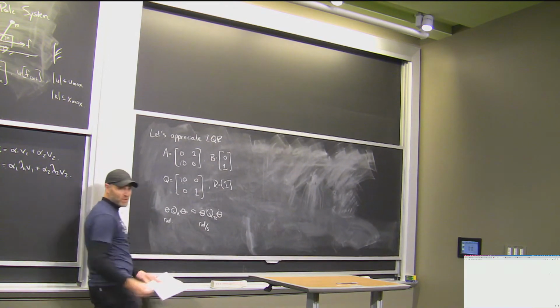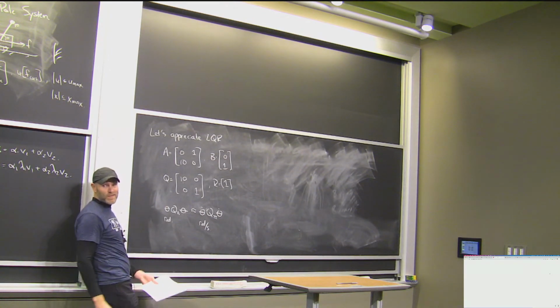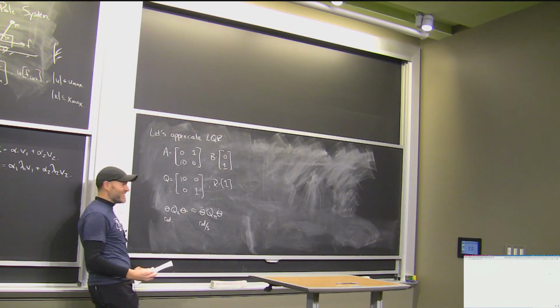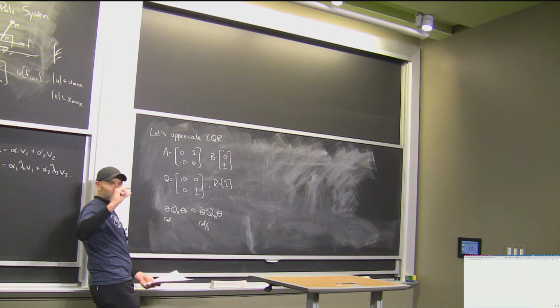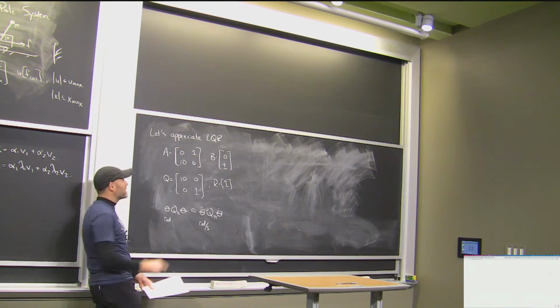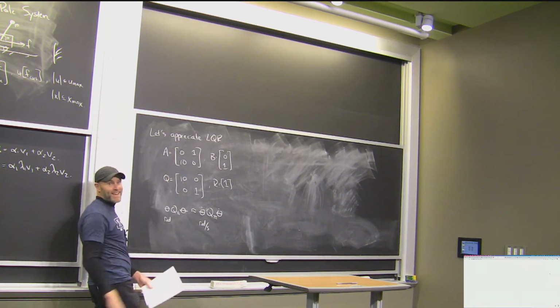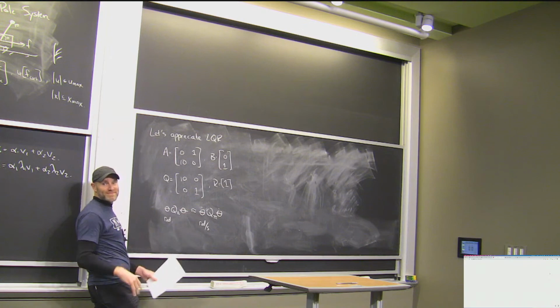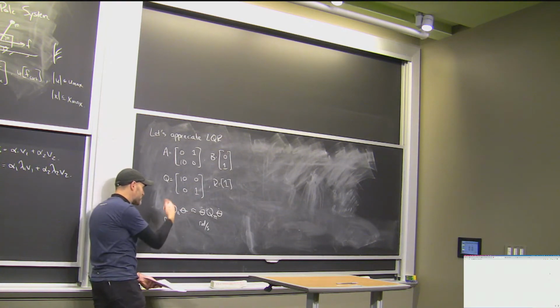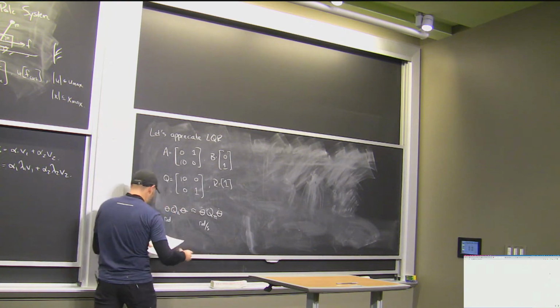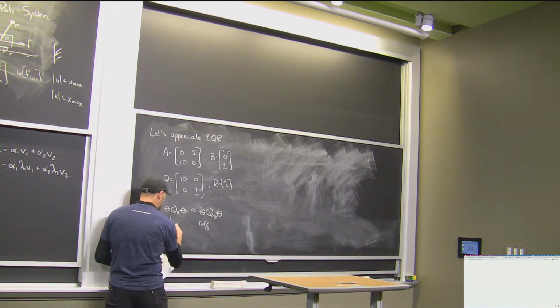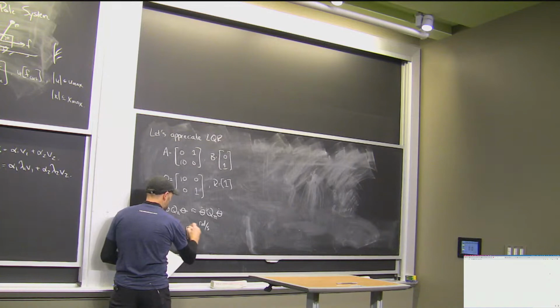Since I tend to build robots that are on the order of a meter long, if I was working on micro robots, I would probably use a different number there. But all of our robots are on the order of a meter. Okay, so my dimensional analysis tells me my time constant is square root of L over G, square root of 1/10.